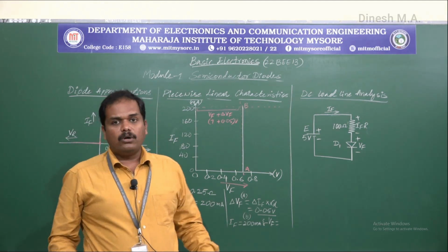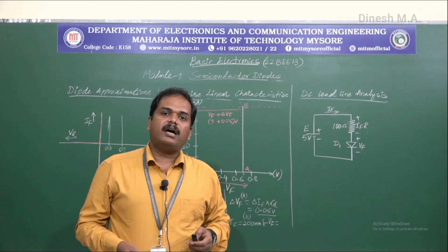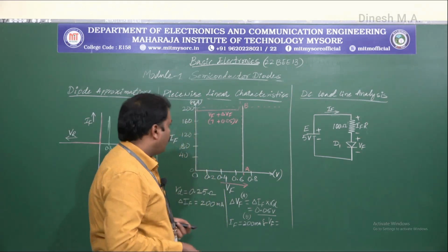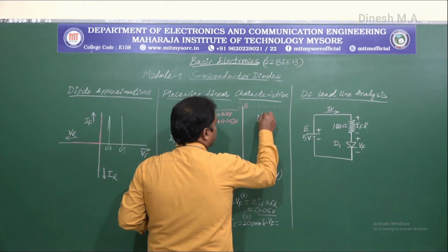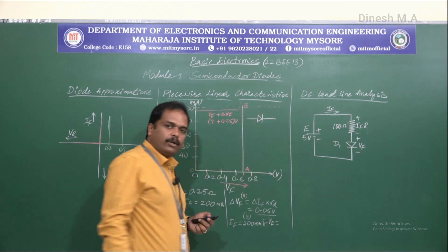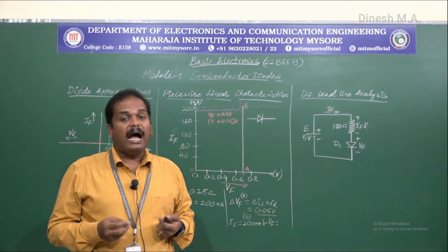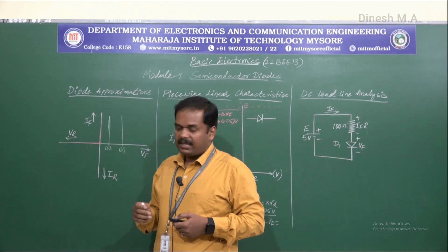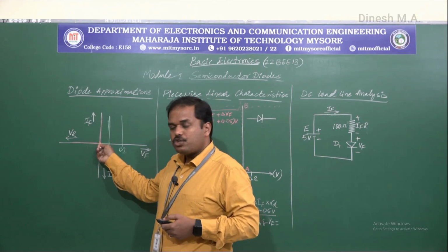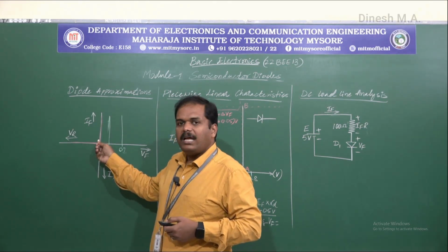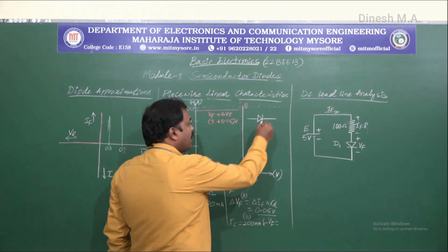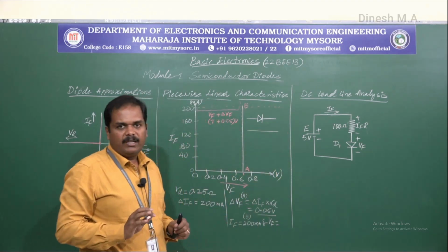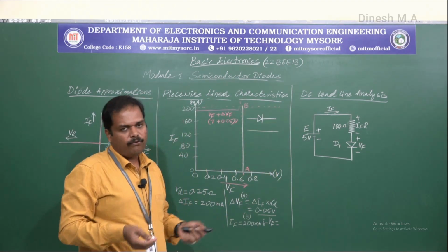So now any diode given can be represented, or we can write the DC equivalent circuit for any diode. For example, let us consider this diode. If this diode is considered to be ideal, as we discussed here, then it would have zero forward voltage drop and zero forward resistance. So if this diode is ideal, then this can be represented as a simple wire, right, which would allow all the current to flow through.